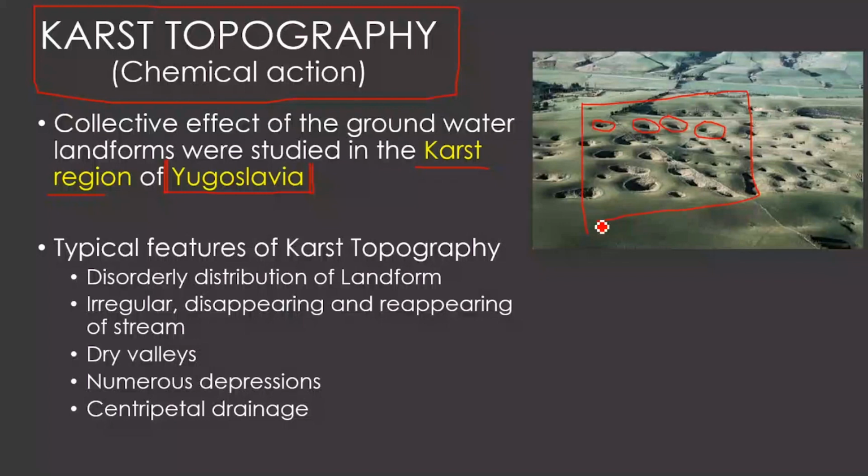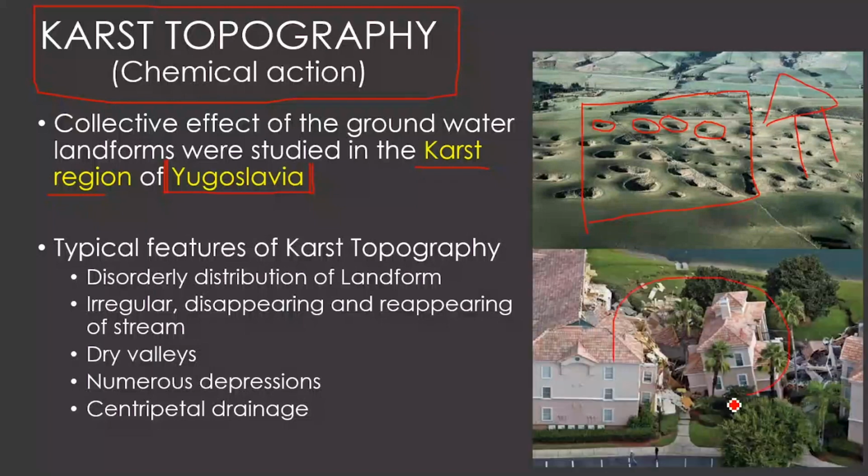If you look at this building where it collapsed, this portion of the building which collapsed, you will be able to see a depression, or a sinking. What happened? The soil, all this part, has moved down. Why does it happen? Because this is the surface and there was some cavity below the surface, and we constructed a building over the surface.